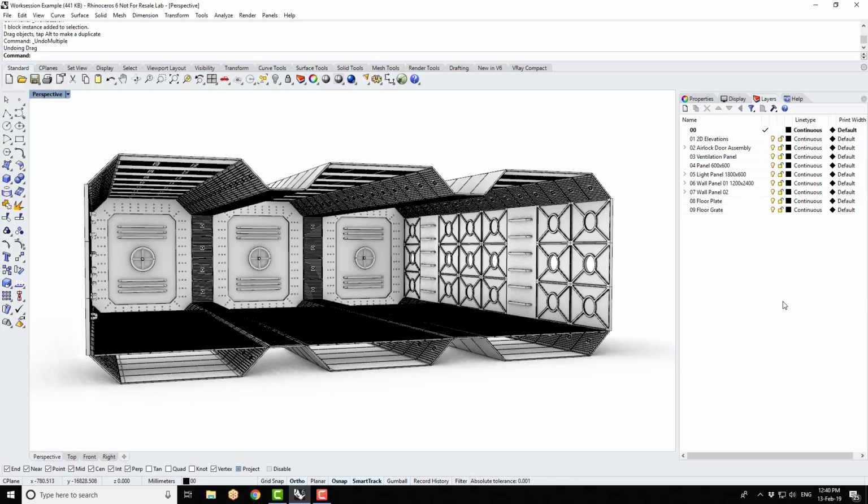Rhino also has the concept of external references, which are called worksessions. In this case, the referenced files are appended to rather than referenced inside the Rhino assembly file. Whilst there is, of course, an overlap as to where one would choose blocks or worksessions as a means of referencing, you could generally regard worksession references as something that you would like to see and visualize, but not directly edit, move, or scale.